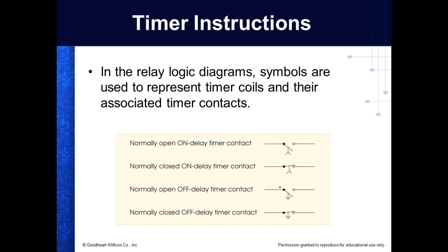No, that's, well, when we draw the connection for the input and the output ports, when we draw what we have connected to those inputs and output ports, we have two drawings in a PLC program. We have the PLC program itself, which has a lot fewer symbols. And then we have the way we connect devices to the actual inputs, right?